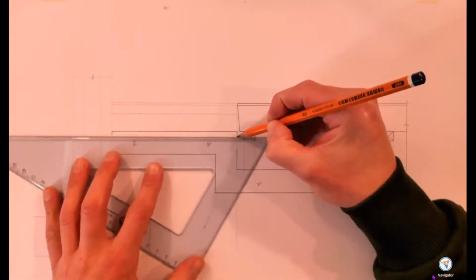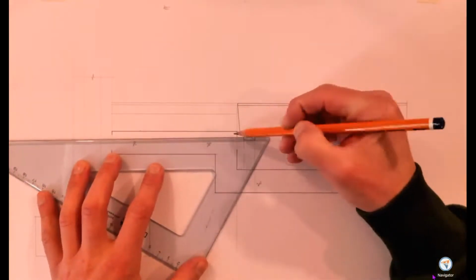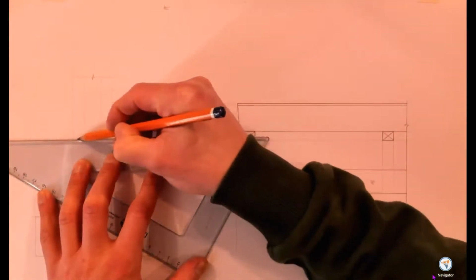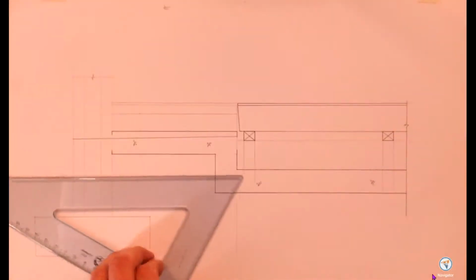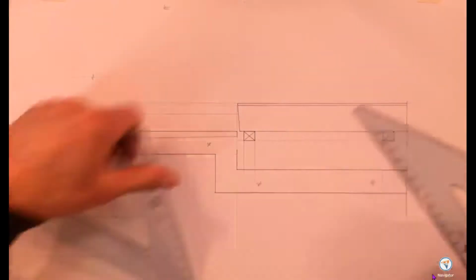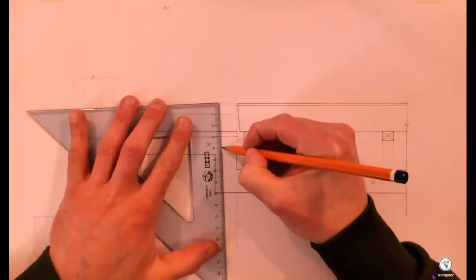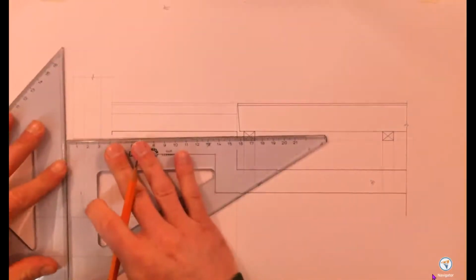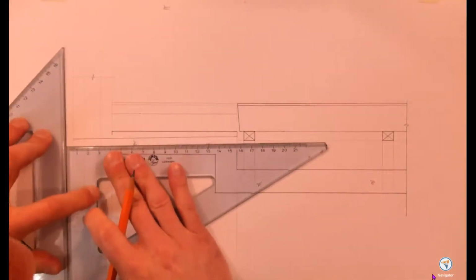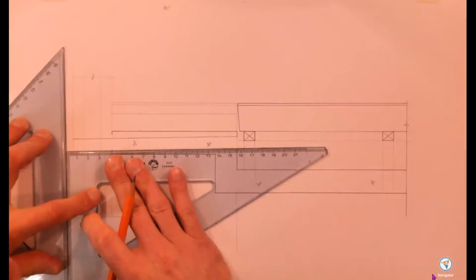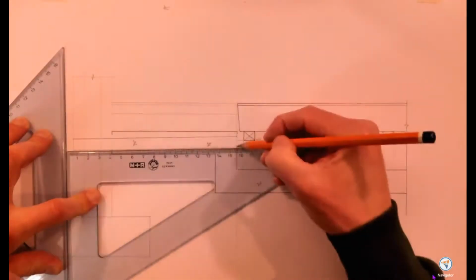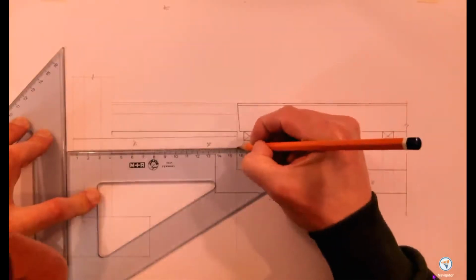So there needs to be a fall on it to stop any rainwater getting in and flooding the floor. So my pipe is going to be drawn in at a slight angle. Standard pipe would be 100 millimeters thick. So I'll just come parallel to that, copy that angle. Angle doesn't matter once it falls out the way, so it needs to fall out towards the outside of the building, and that is my pipe drawn in.